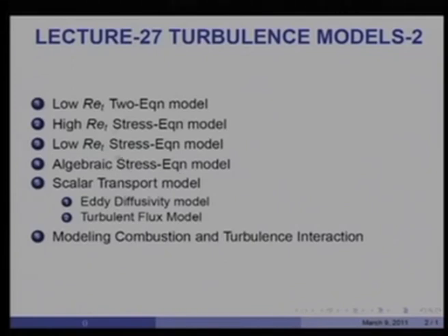This would complete our discussion on how to model a stress, but likewise we must also adopt a strategy for modeling turbulent scalar fluxes, and again there are the eddy diffusivity models and the turbulent flux models analogous to the eddy viscosity model and the stress equation model. Finally, I will show a couple of slides on how to model the interaction between combustion and turbulence.